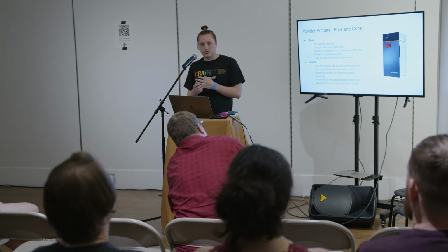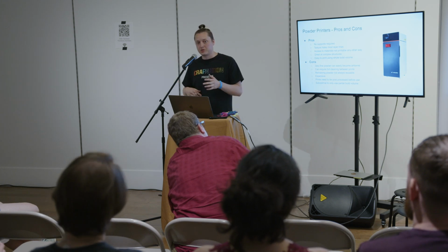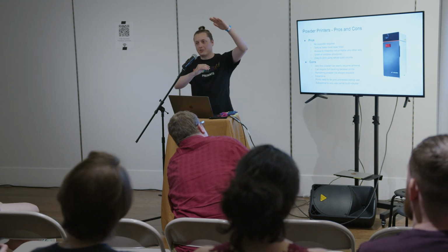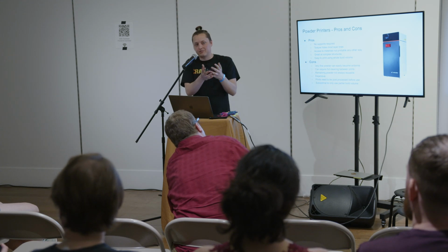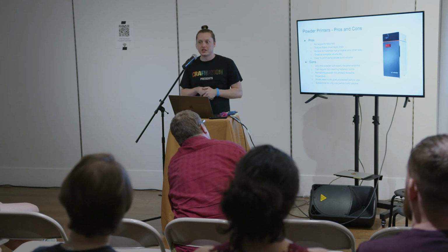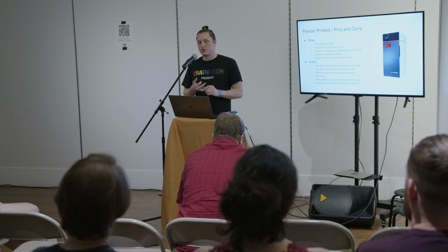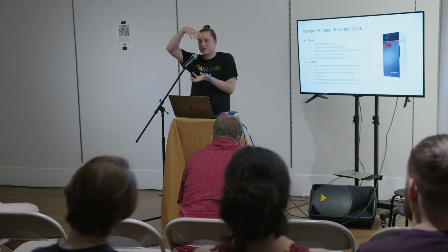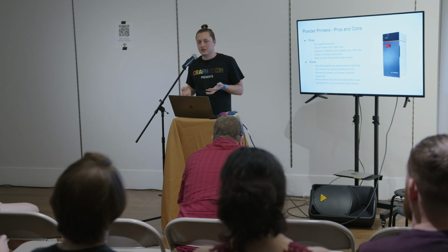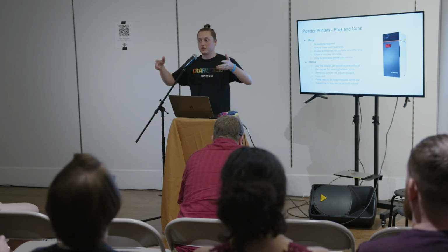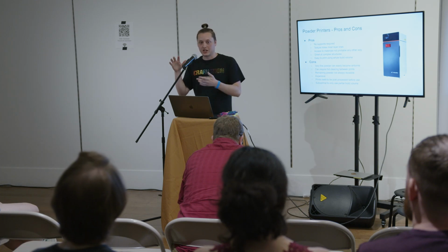And then it's really easy to fill the entire build volume. With most printers, stacking things on top of each other means that you have to break them apart and do things like that, which can be a lot more challenging. Whereas with the powder, since everything is suspended in the powder, you can use the entire build volume, filling it with all of the same object.